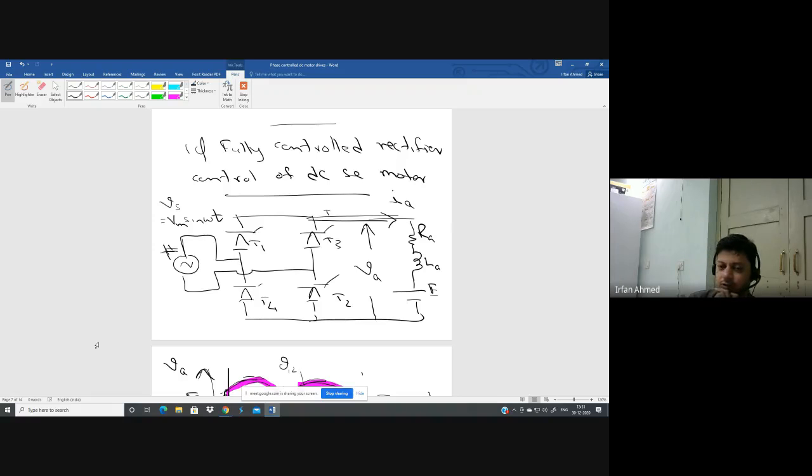Yes, to control one motor, you needed one more motor and one generator. Right? So the cost was too much and the space required also was very high. Okay? That was the disadvantage of Ward-Leonard method. But the advantage was you could get linear speed control over a wide range and there were no harmonics introduced into the supply. Okay? That was one method.